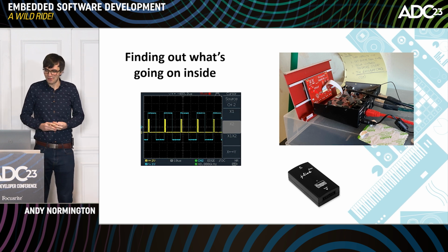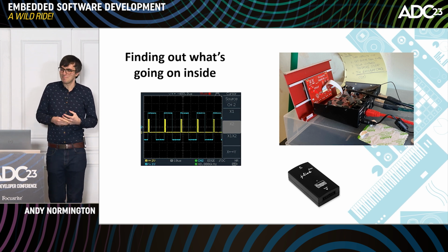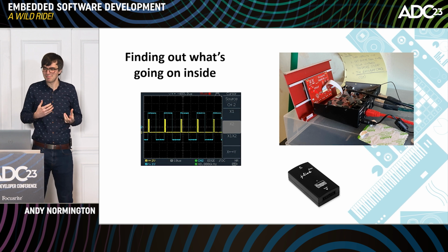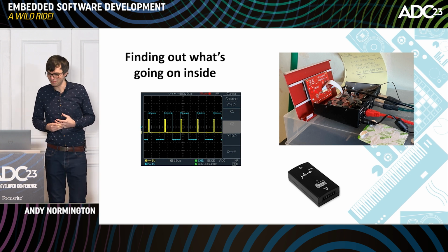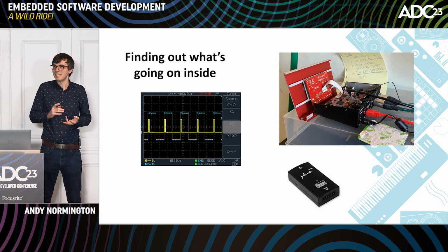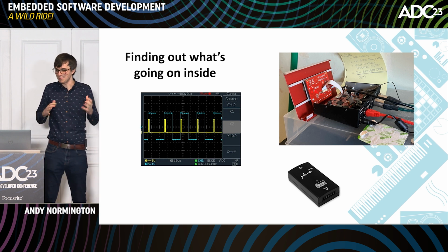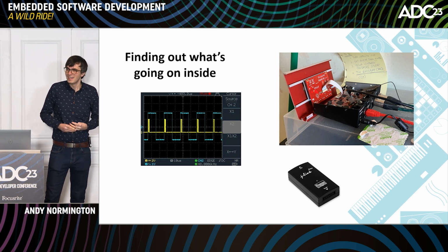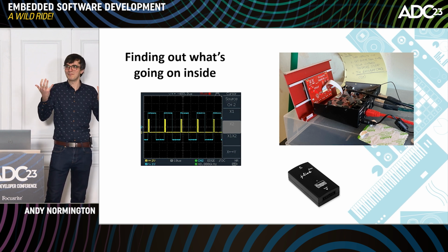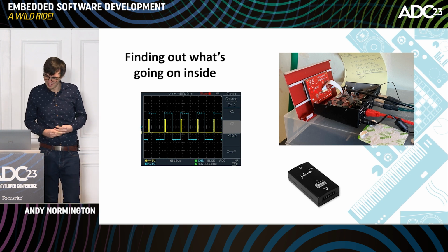There are some traps involved in that debug access. You can get catches to fall into, I guess, with pausing execution on a real-time system like this. If we set a breakpoint, but we have real-time interfaces dealing with USB and network links and stuff like that, we'll time out, we might make the problem go away or might cause new problems that stop us seeing the problem we're trying to debug. Something as simple as if we're strobing LEDs, if you pause in the wrong place, all your LEDs are on full power, you can't see anymore, and the power system's clapped out because it was never designed for pulling that much current in one go.